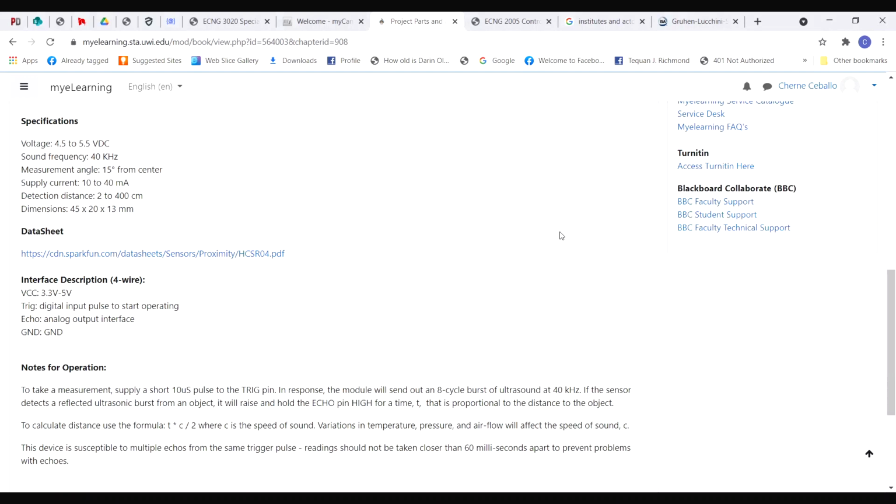So, do you think that's something you could write a program to do? If I go back to notes I made, I think, yeah. So if we wrote some pseudocode, right? Step 1 would be make whatever pin I'm connected to an output. Step 2 would be output a high, right? Step 3 would be wait for however long I have to wait. Step 4 would be output a low. That sounds doable, right? Yeah.